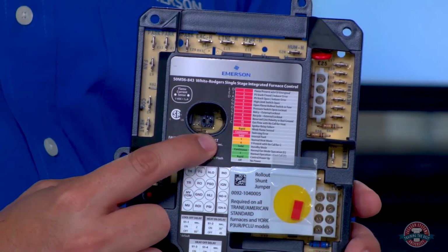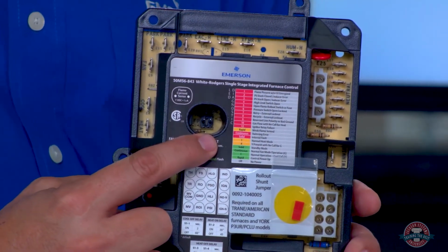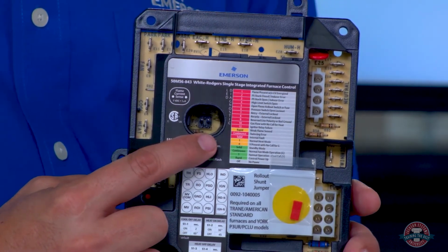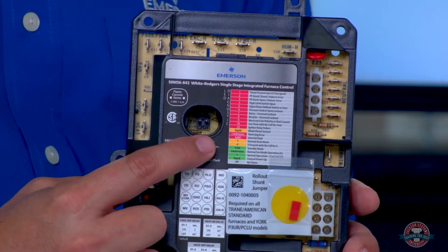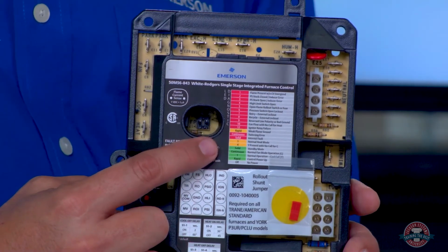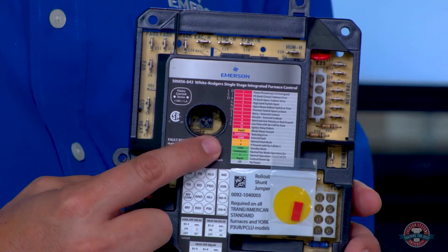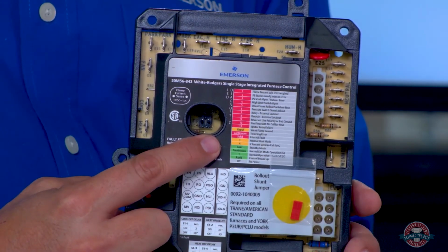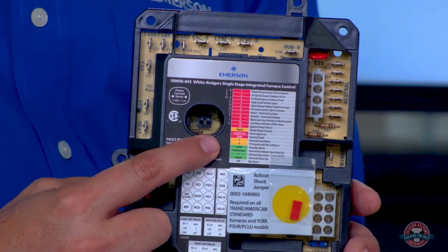Our universal controls, all of our IFCs here that do both the ignition and the blower, they either have these pins that come up off the board, or they have pads, little flat spots on the board itself to put your meter on, and you can test your flame sense without pulling your wire off. And one final benefit of that is if it's the spade connector or the wire that's giving that weak signal and you pull it off to do your test, you may not see it.